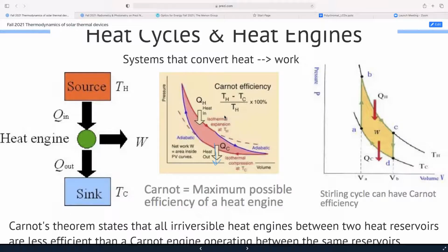Then you have an adiabatic compression happening in this part, where again the volume is decreasing, but now the pressure is increasing much faster. You're allowing the temperature to actually go up. You're not maintaining the temperature. Of course, we didn't talk about physically how we're doing it because that's not important. We're abstracting it into a cycle. And this, of course, physically happens because you get work done by the system.